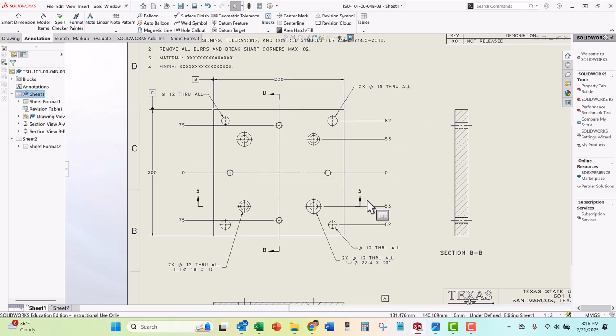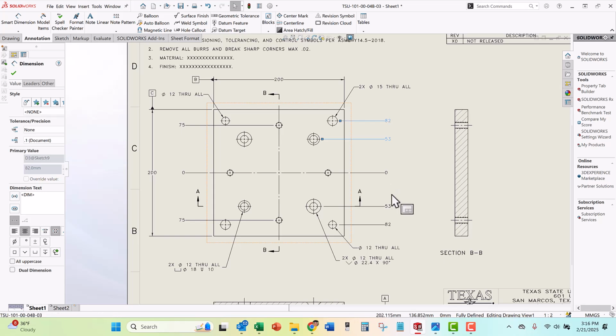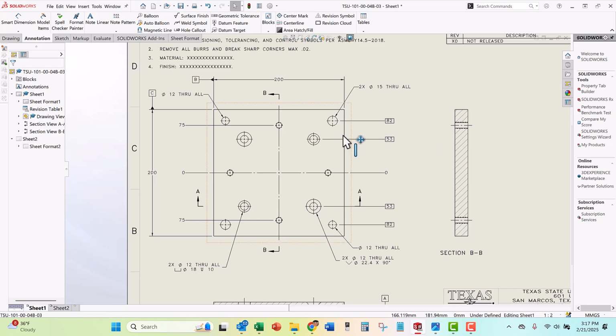So that's pretty handy. All right, I've got the datums. These are going to have to be basic dimensions because I need my trifecta. To locate these holes, I want to define the datums. I've done that. I want to define the hole target locations with basic dimensions, which are perfect, no tolerance. So I want to select all the dimensions that locate those holes. I haven't selected all of them, but you'll get the idea. Change this to basic. Now those all have basic dimensions on them.